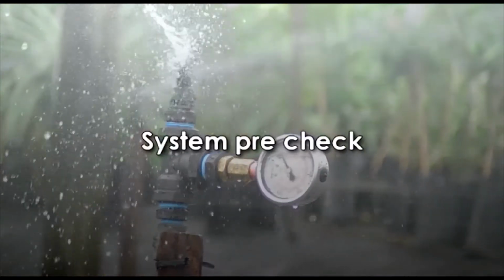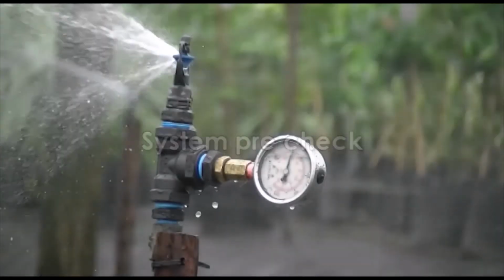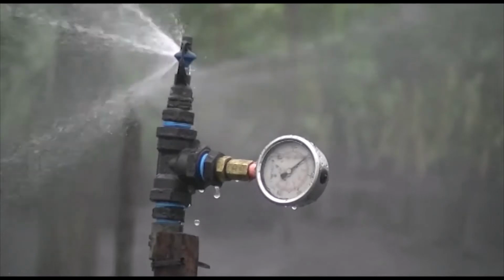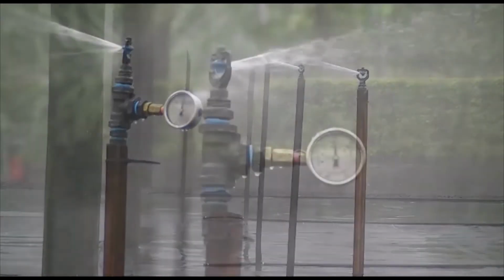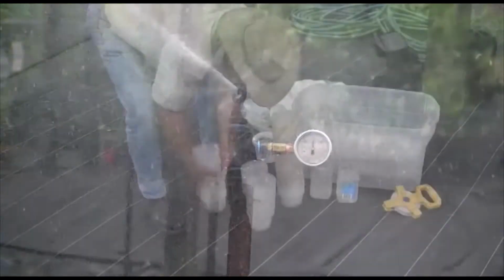The system should be operated for a short period of time to ensure all components of the irrigation system are performing correctly. Be aware of correct system pressure, sprinkler blockages, filter pressure losses or backwashing, competing irrigation events, and other factors that may affect the result. Once the pre-check has been completed, reset the system.